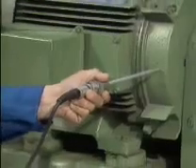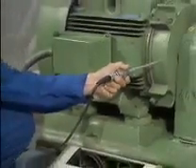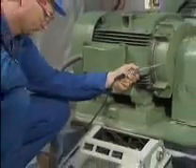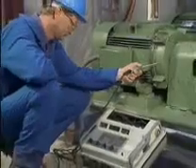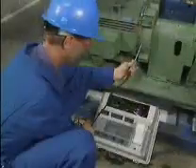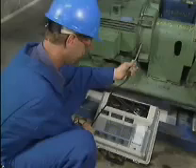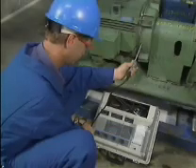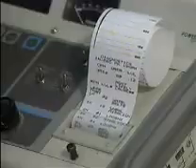Baseline data that is taken before repairs are made can be compared with subsequent readings to determine if the problem has been corrected and to check the quality of the repair work. Data that is taken after the repairs have been made can serve as new baseline data for future readings and comparisons. Now's a good time to check your understanding of the basic concepts of analyzing vibration.